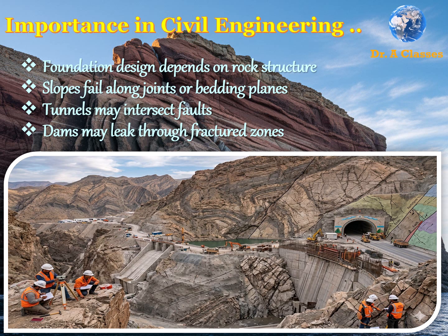If a foundation is placed on layers dipping away from the structure, it could slide. Look closely at the tunnel entrance and the dam abutments. We have to map every fracture and fault that intersects these sites. A tunnel that cuts through a weak fault plane is a tunnel at risk of collapse.